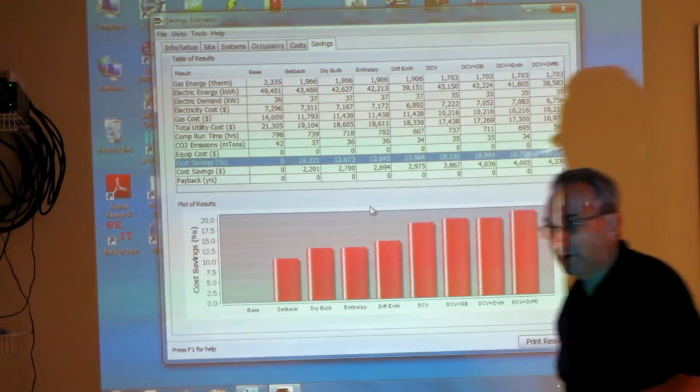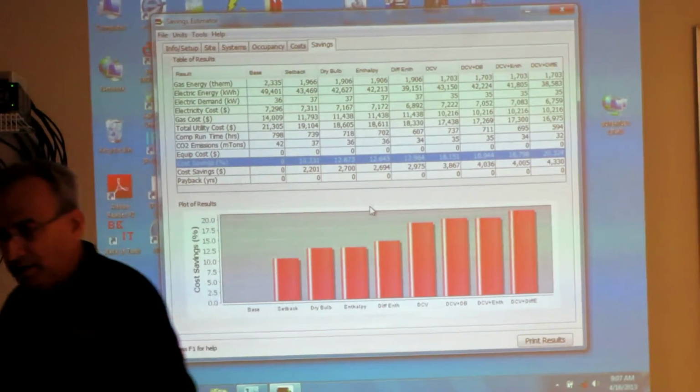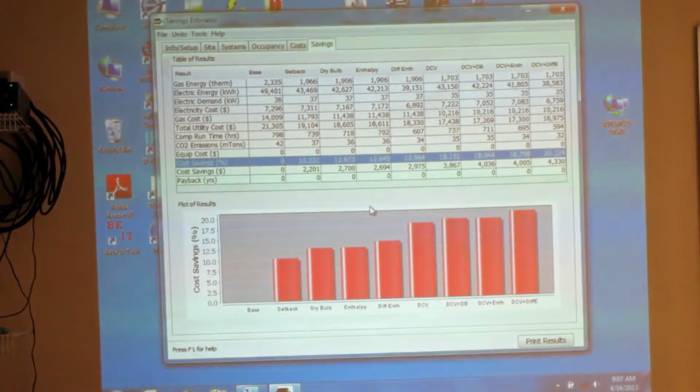So if I took an economizer and outside air sensor, return air sensor, discharge air sensor, probably new dampers, put a new damper on, actuator, put it all as a kit, I could probably put that in for a couple grand. Easy. I got a 6-month payback. And that's based on that normal occupancy curve? Normal occupancy curve. And you can change that around to match whatever the customer has.